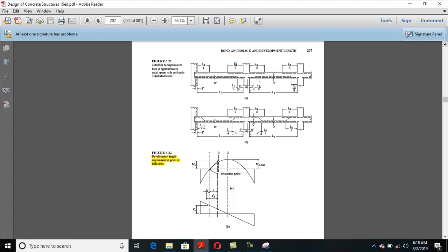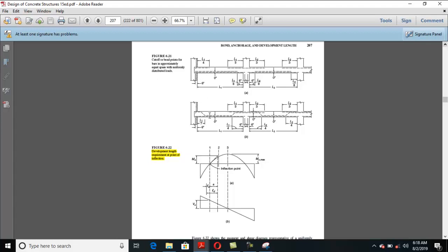If these beams are subjected to UDL and these spans are uniform, you can use these coefficients. So for negative reinforcement, you see that this length L1 by 4 will be the actual cutoff point, and this is 1/3 for the other. This length divided by 3, and this length divided by 3. The bar should be extended for 6 inches. This is for the bent-up bar.